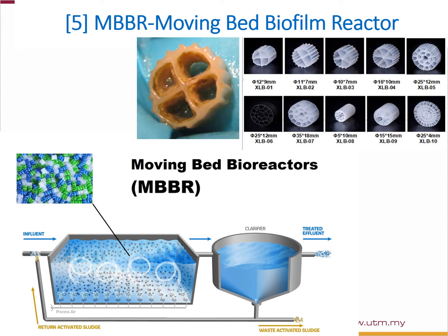Another advanced treatment, considered quite advanced as compared to the conventional method. It looks like you just need a big tank filled with lots of the carrier. Looks like this. It is designed to create a lot of surface area for the attachment of the biomass, so that after attached it looks ugly like this. It looks like a mooncake to me.